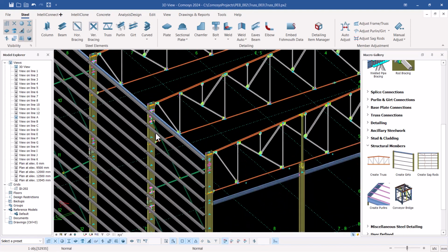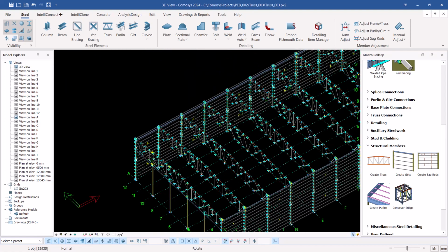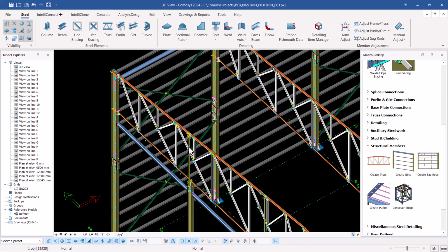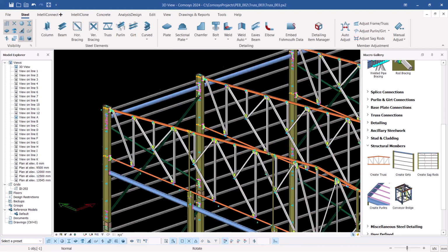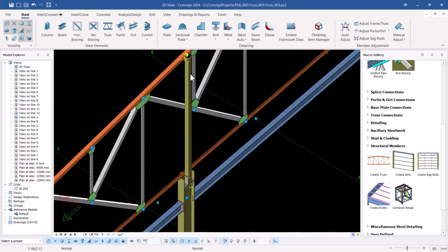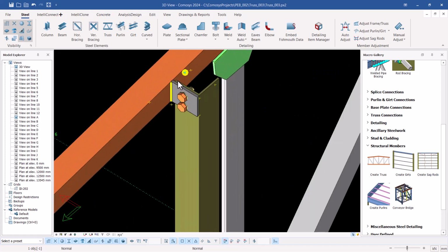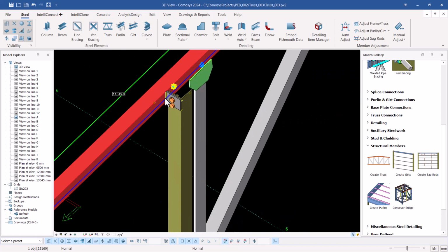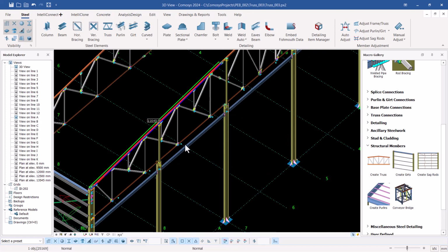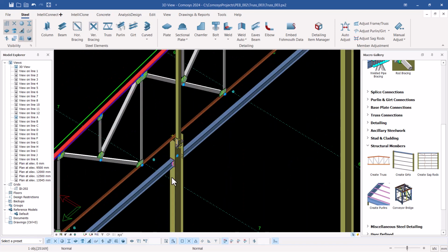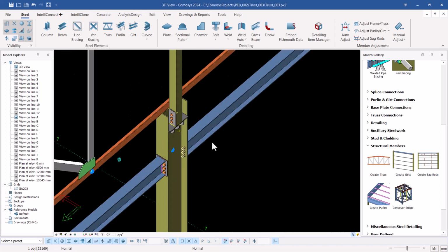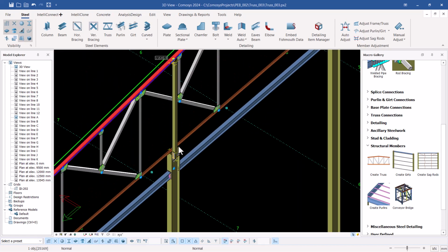As easy as that. So what I'm going to do, I'm going to place purlins or guards on the cable side. So let's start with the side that I think will be somehow complicated, because I had created the extension here that goes up and gets connected to the top cord of our truss, so that we'll cover this with iron sheet nicely. So remember, the column could not go all the way that way, so we had to create some details that will help us do that nicely.